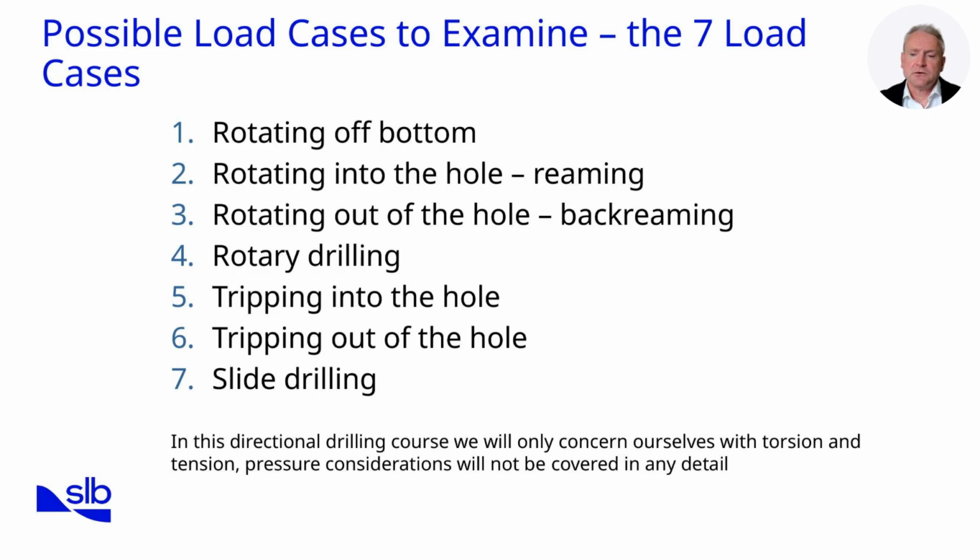In this directional drilling course, we narrow our scope to torsion and tension because these dominate drill string design. Pressure-related load cases such as burst and collapse will be introduced later. By focusing first on torsion and tension, we establish the foundation of overload design before layering in more complex load interactions.